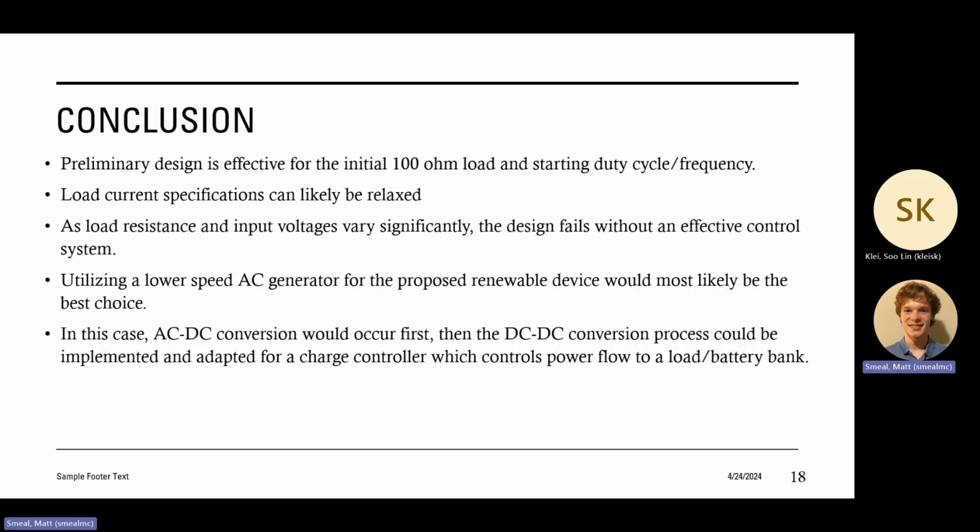So for our conclusion, the preliminary design is effective for that 100 ohm initial case and for the starting duty cycle and frequency. Those low current specifications aren't necessary. We didn't even get near 3 amps. But if you had multiple devices, that might be good to keep in mind. As for the load resistance and the input voltages, though, when changed, the design fails without any control system. So it's got to have a control system.